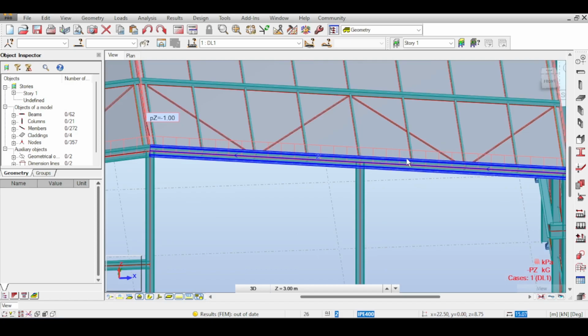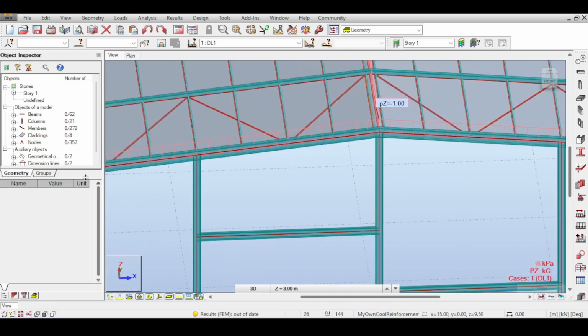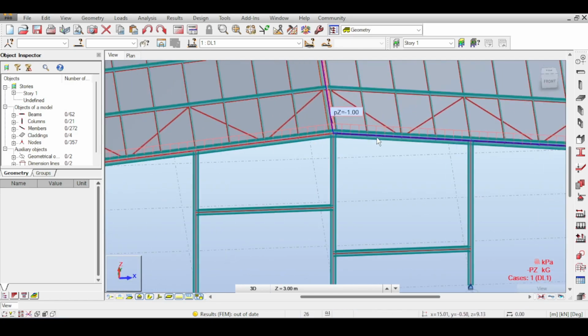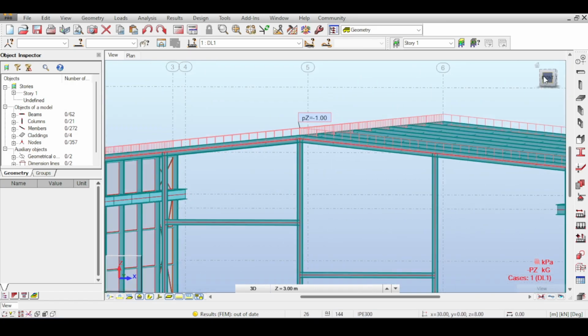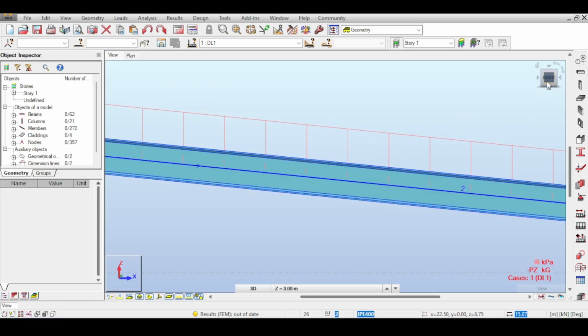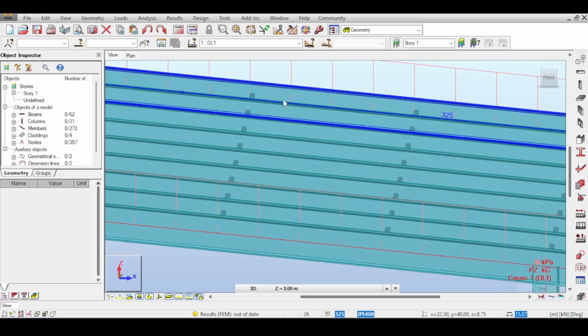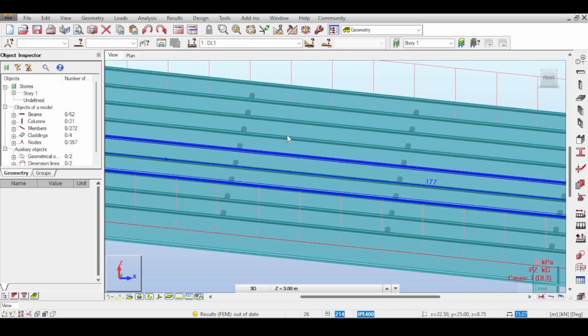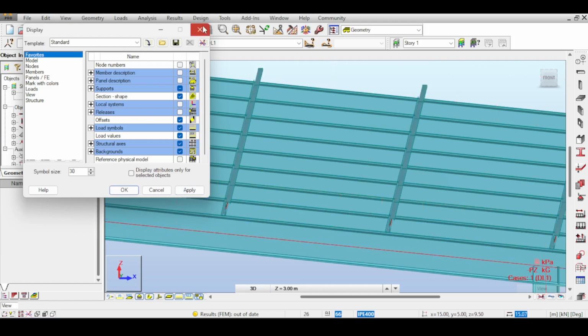Now, here there are multiple options. I can just basically put one continuous portal frame here, but then you would think, wait a minute, this makes the portal frame section smaller. You're right, and this will cause some issues with regard to practical considerations, because in practicality, the top surface of all the frame elements, portal or gable, should be exactly on the same plane, because you want to provide purlins. So the height of the top surface of all the elements should be the same so that you can provide smooth purlins above them, because the purlins are above your portal frame sections.